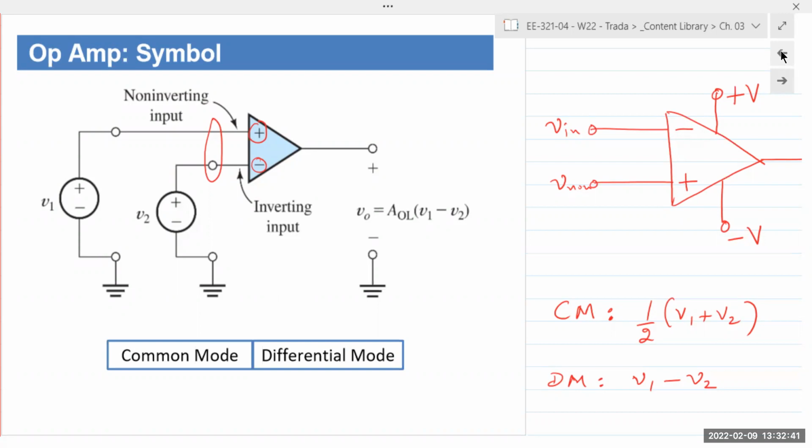There is a term associated with this, and I'm jumping a little bit ahead and going on the side. It's called common mode rejection ratio, CMRR. That is a spec of every op-amp circuit. It basically tells us how good the op-amp is at rejecting a common mode signal. Meaning, if the same signal appears at both input terminals, those signals should be rejected. All right, does that make sense? Does that answer your question? I know there's still some confusion, so please feel free to ask.